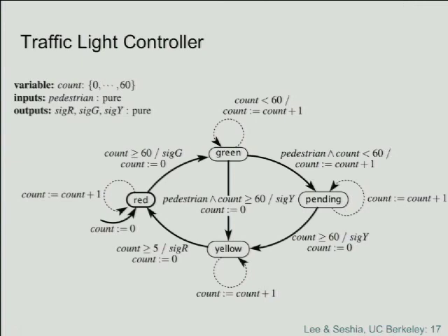And the issue is that the guard on the highest priority transition is what you evaluate first. If it's true, you take it. If it's not true, you look for the next highest priority transition. And if its guard is true, you take that. Now, you don't actually need priorities, right? I could write this as an ordinary transition and augment this guard with the pedestrian being absent. But the problem is the notation gets sort of more complex. So the dotted line is just a shorthand for that augmented guard. Does that make sense?